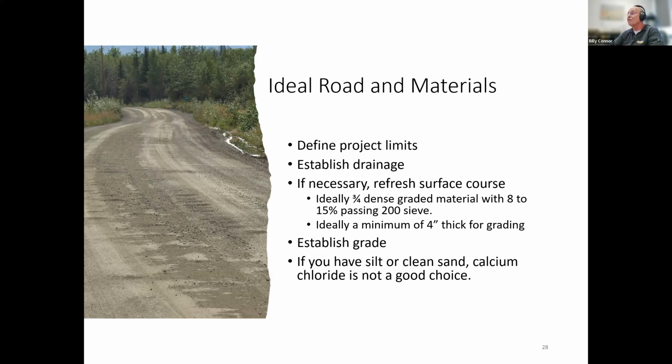So then you want to establish your grade, including your crown, and make sure that the roadway is ready to receive the calcium. And if you have silt, calcium is not going to be a good choice for you, because the silt with the calcium in it is going to attract water, and it's going to turn to mud. If you've got clean sand, basically what's going to happen is the water's going to run through your sand, and the calcium chloride is going to go with the water, because it's going to be diluted.